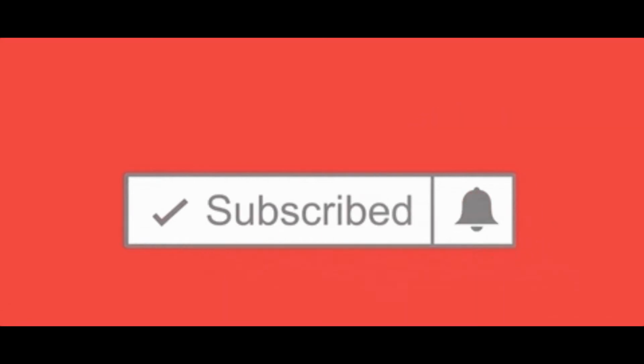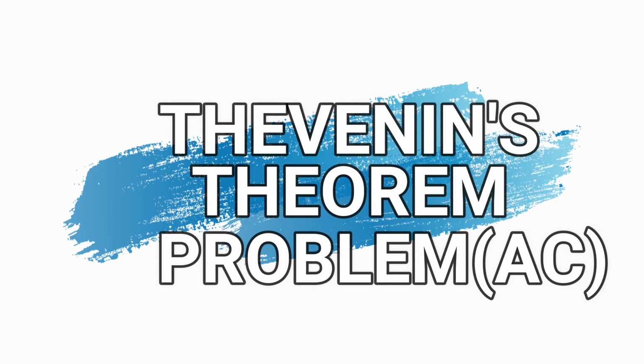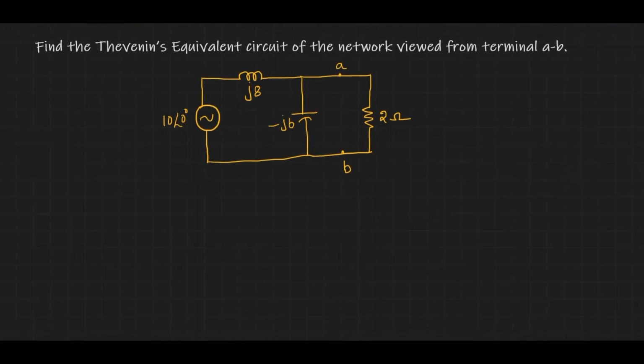So here we go to the Thevenin theorem problem for AC network. Before taking the problem, we must know the statement of Thevenin theorem for AC network. Any linear active bilateral AC network can be replaced by a simple equivalent circuit having a single voltage source VTH in series with a single impedance ZTH. This is the equivalent circuit.